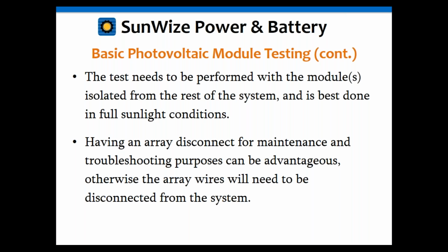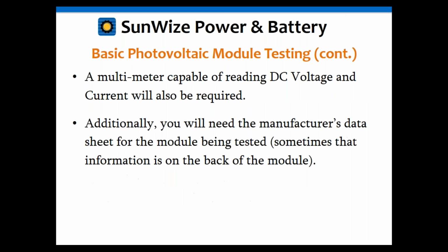We talk about the short circuit current test. The other thing about it is those wires are live. So when you disconnect it, when you have this in your hand, you have to always keep in mind that now there's a shorting hazard as well. So again, trying to have a disconnect in there like a circuit breaker or a switch of some form is really nice to have from a maintenance or troubleshooting perspective.